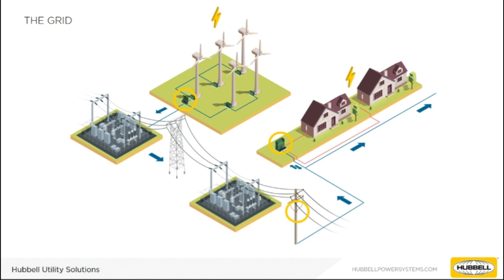In this image, you can see the intention of underground distribution with houses that have hidden underground lines versus each house having a utility pole in their backyard. Instead of a pole, you would see a green pad mount transformer with the inserts and elbows that we discussed earlier. That transformer is then connected to a feeder line coming off of a distribution line. The transformer can provide enough power for up to 10 houses. This is why you might see multiple transformers on the same street.